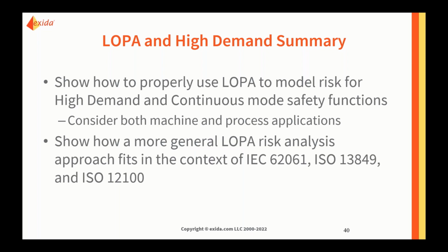Is there any relation between a LOPA and a bow tie? Yes. A LOPA is a single path through the bow tie. The bow tie is a combination of event escalation sequences that often tie together at a loss of containment point in the middle with various different potential outcomes resulting from that. Each one of those lines all the way from the left side of the bow tie to the right side of the bow tie can be done as a LOPA. And then when you combine all of those things together, that's what you get with the bow tie.